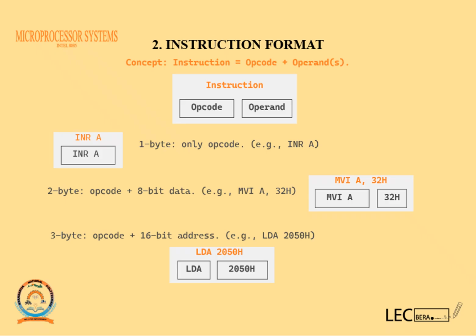So what does this mean? It means that the smallest instruction you can get is an 8-bit instruction, and that instruction is going to contain what? Only opcode. Instructions which are 16 bits to 32 bits in length contain both opcode and operand. Opcode is the instruction itself, like move, increment.